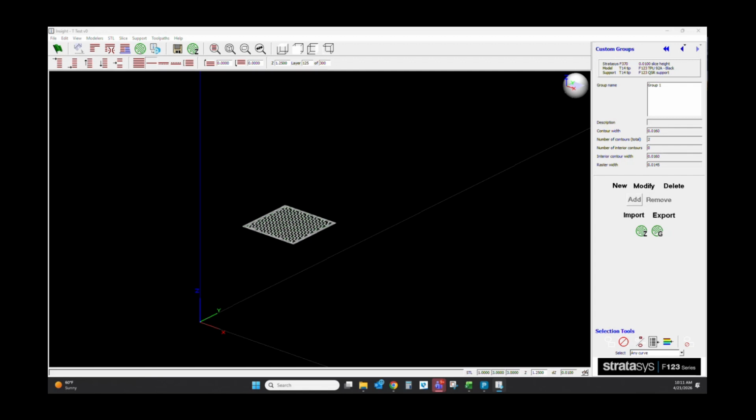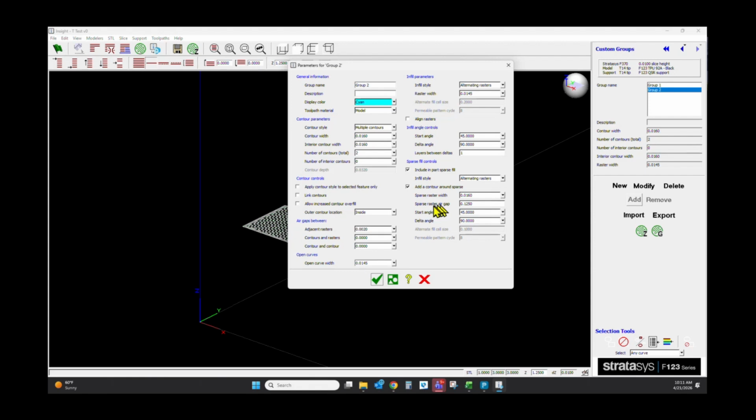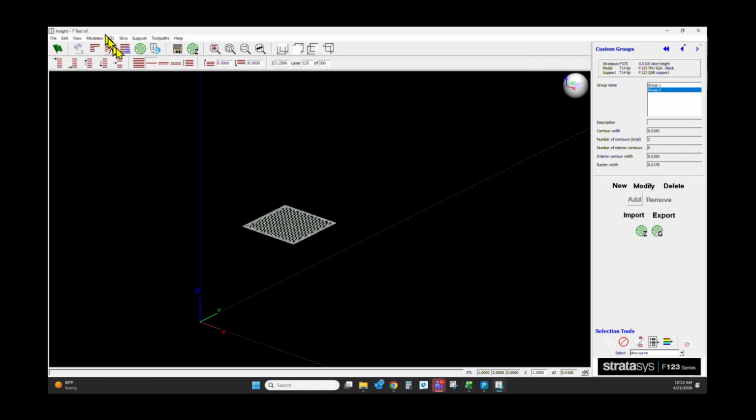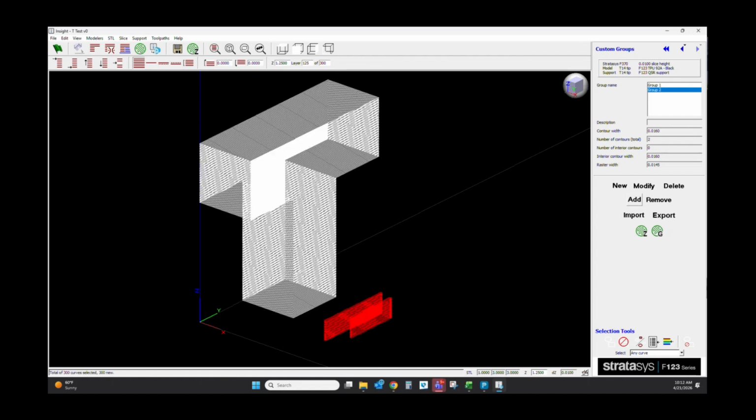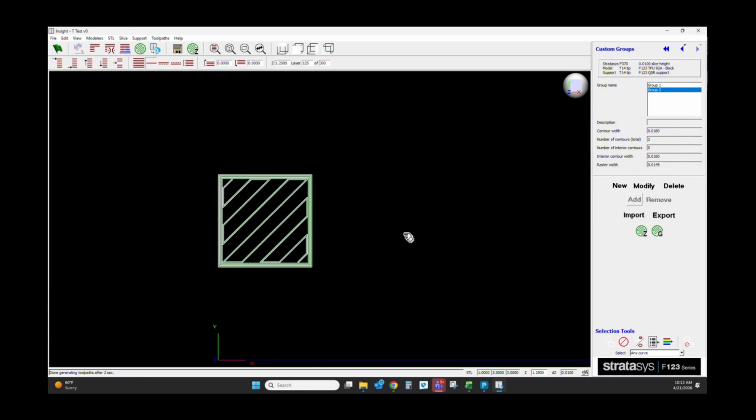It bumped off screen. I'll pull it right back here in a second. Here. I made my adjustment. You can see that I added a sparse raster air gap. So now the center line to center line spacing will be 125 thousandths. So I'm going to apply that to this entire block. Add group. So as you can see here, that's a pretty wide open infill.